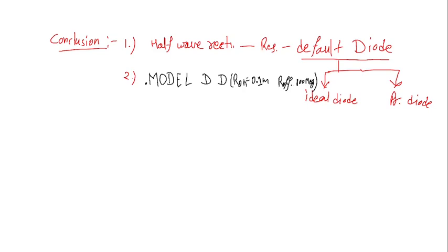So this is the command for that, or you can use the forward, I mean built in voltage, but I am not using it here. Remember, this D is a variable name. Whatever diode name you are using here, suppose this here is D1, and the model name you have written is D, then this should be proper.